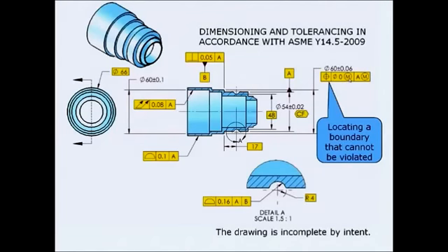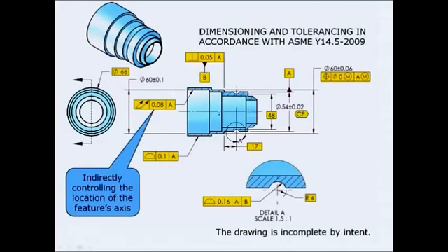Could have been circular, happens to be total with the 2 arrows. And it's saying I want to check the surface to make sure it's not varying too much relative to this axis. So it's picking up form variation, changes in size, and if it's not centered. So kind of indirectly, this runout is keeping the cylinder centered on the datum axis. That's it. It's really not that tough to control the location of your features.